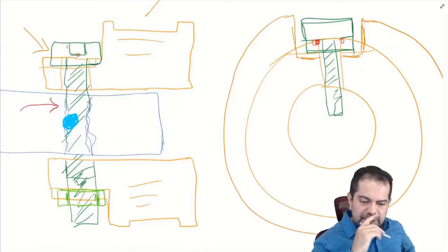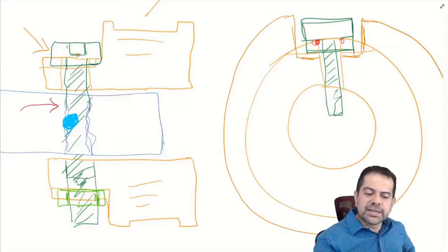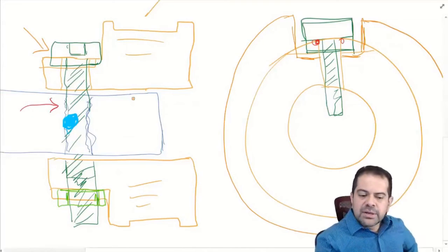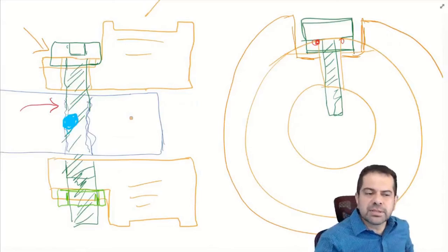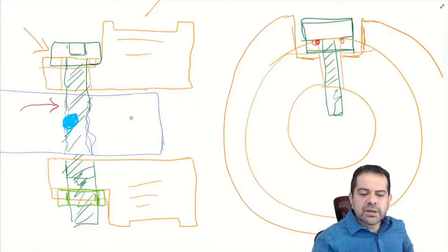And there was something else. Another thing is, a lot of these motor shafts, or any other shaft that you deal with, if the material is very hard, then it's harder to drill and tap through that material. Capable companies will do it. More experienced companies, or any company that has enough knowledge, is able to drill and tap through hard material. However, it's a little bit more costly.